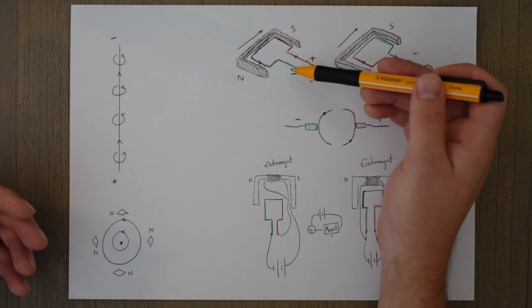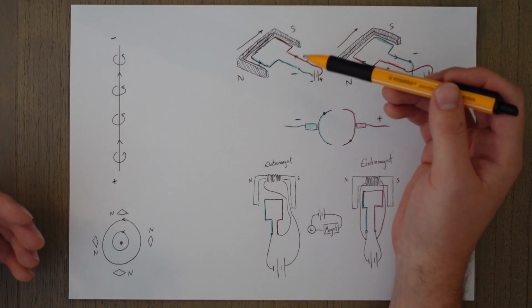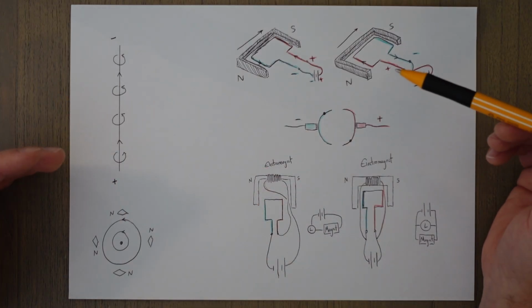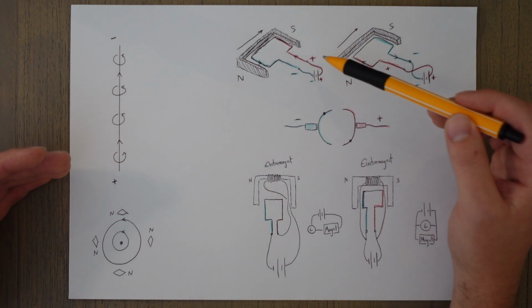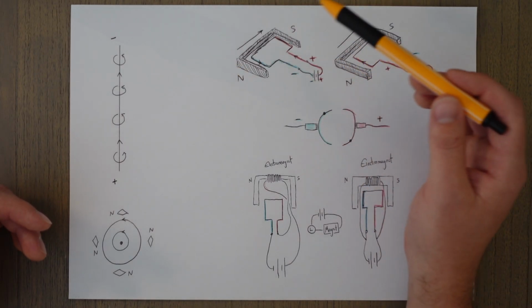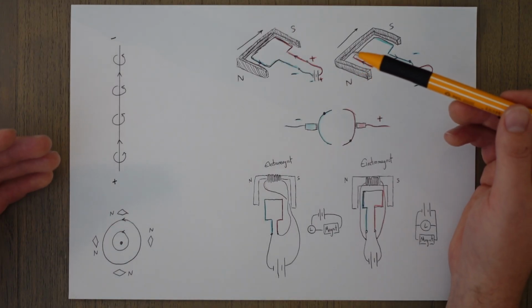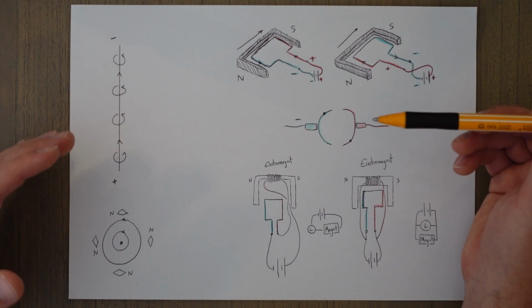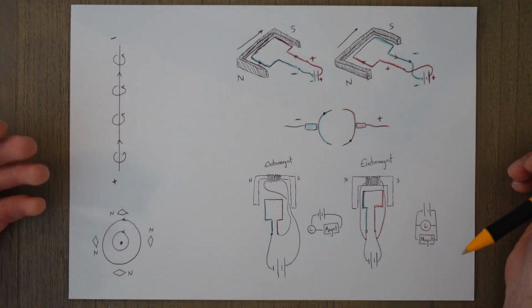And if we make a loop of wire and put it inside a U-shaped permanent magnet, then we can start to see the beginning of how a motor works. Let's start in a position where we have a loop of wire lying flat inside this U-shaped magnet, with this as the north and this as the south side of the permanent stator magnet. When we send current through the loop, it can get a bit confusing because the wire will start to move because there's two magnetic fields interacting with each other.